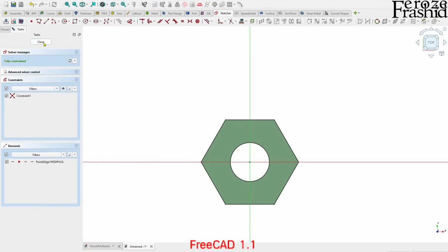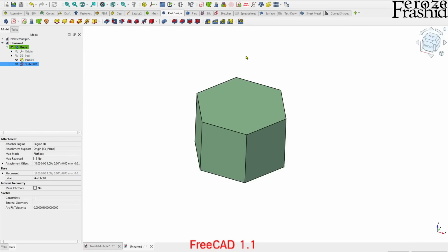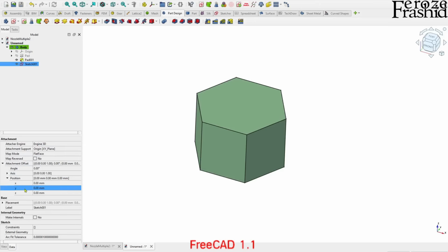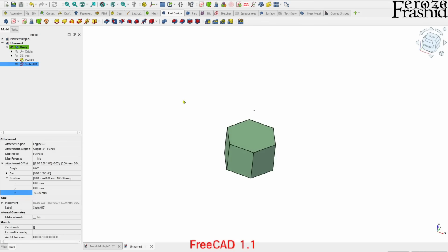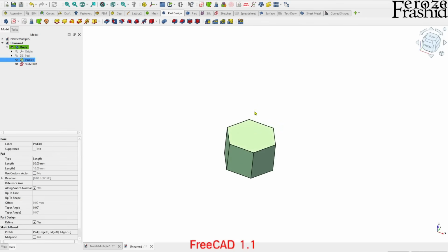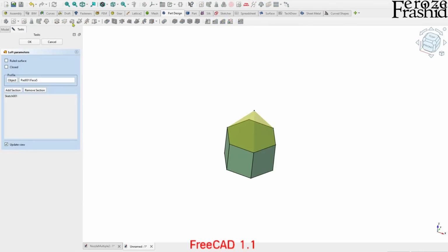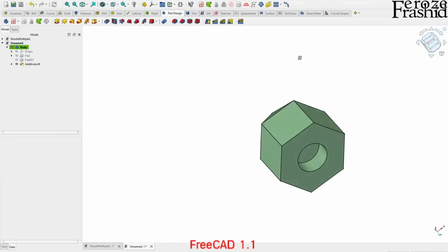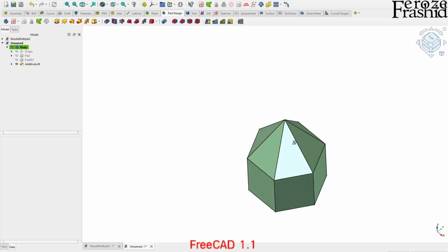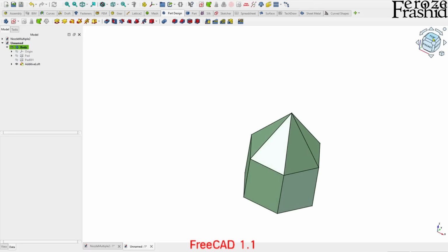So that's my sketch, and this sketch I want to pull it up somewhere here, maybe 100 millimeters in the Z direction. So on Z, let's make it 100 there. That's my tiny little spot. Now I want to take this surface and take the point and make it a loft there. Very simple. So the whole thing we did with, like, 2 sketches, no datum plane involved. So that's one pointer if you want to take a note on that.